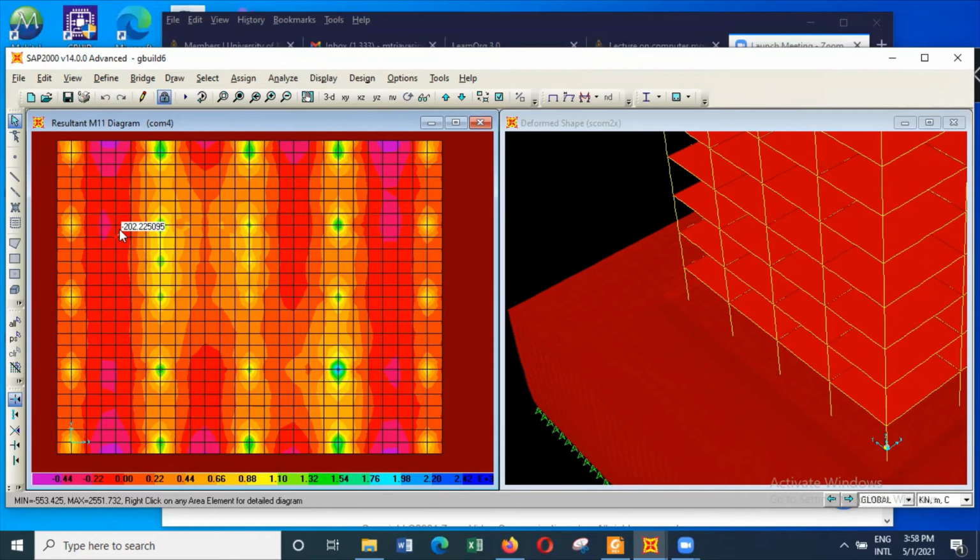Because earlier we considered it as sandy soil, dense sandy soil, and the bearing capacity is about 150. And generally for a bearing capacity of 150, you get a higher elastic modulus, because sandy soil can give a bearing capacity of 150 when it is fairly strong or dense sand, not loose sand.